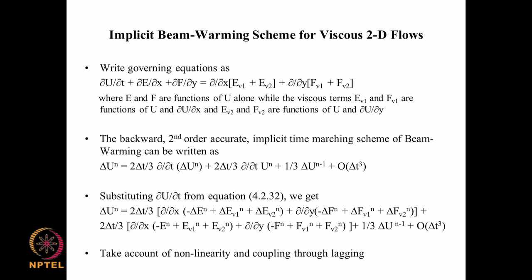So, for viscous 2D flows, the governing equation is not just the left hand side equal to 0, but we also have viscosity terms here, and here we are making a distinction between viscosity terms Ev1 and Ev2, and similarly Fv1 and Fv2.